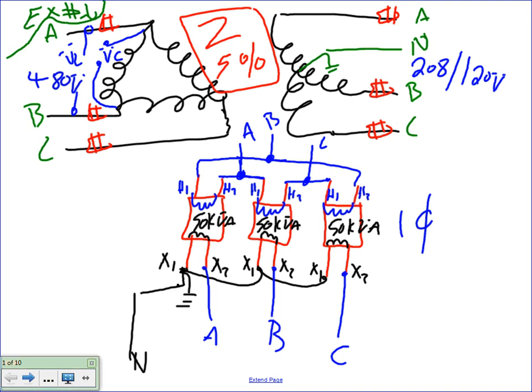Everybody knows the difference between line to line. Line to line voltage is between the phases, phase A and phase B. Coil voltage is right across the coil. This baby here is called the coil, right? We know that from the beginning. So this is the delta. On the other side, I have a Y. So the center of the Y is always grounded to both ground and neutral, and we get A, B, and C. Every system starts with a transformer.